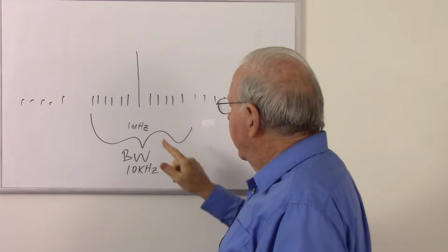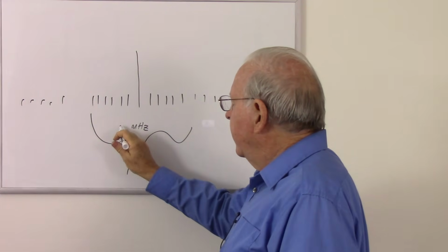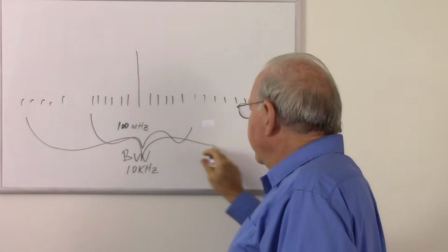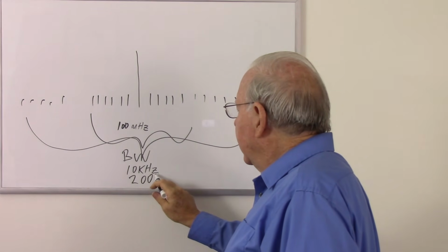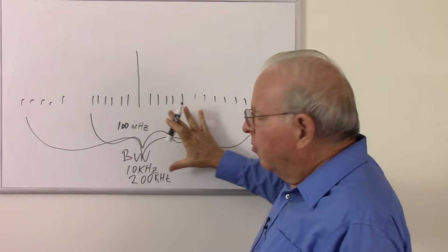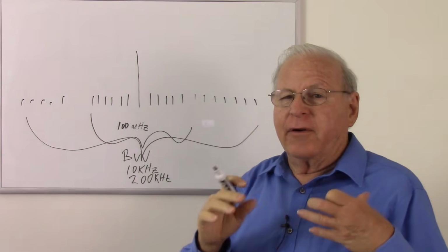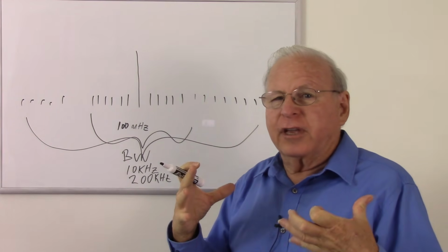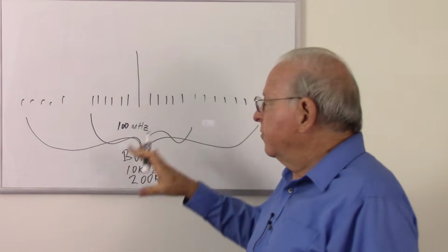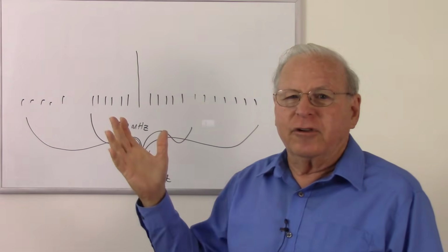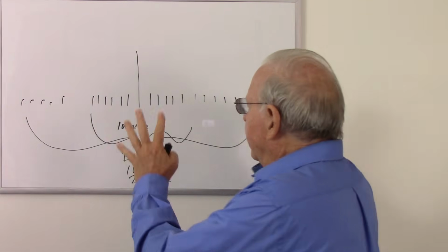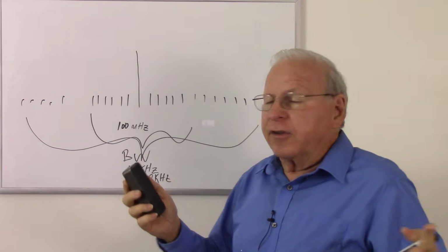But now let's change that to FM, where our typical carrier is 100 megahertz. Now our bandwidth gets a lot wider, to be about 200 kilohertz. Well, that's way more than enough to carry the human voice. In fact, on FM radio, we can carry 2 channels of stereo music at high fidelity, with the music sounds going up to 15 kilohertz, and we still have room left over to carry other information. They used to use it for pager signals, elevator music, all sorts of stuff. I don't know if it's still done, but that used to be incorporated into FM radio because we had all this bandwidth to play with.